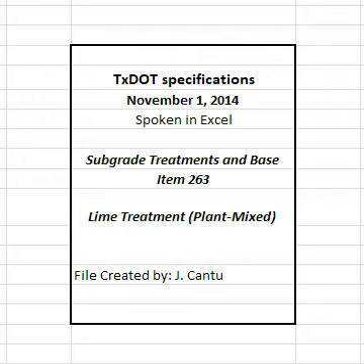4.5 Finishing. Clip, skin, or tight blade the surface of the lime-treated material with a maintainer to a depth of approximately 1/4 in immediately after completing compaction of the final course. Remove loosened material and dispose of it at an approved location. Seal the clipped surface immediately by rolling with a pneumatic tire roller until a smooth surface is attained. Add small increments of water as needed during rolling. Shape and maintain the course and surface in conformity with the typical sections, lines, and grades shown on the plans or as directed.